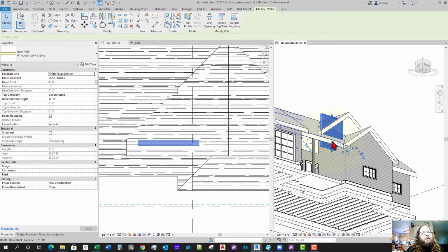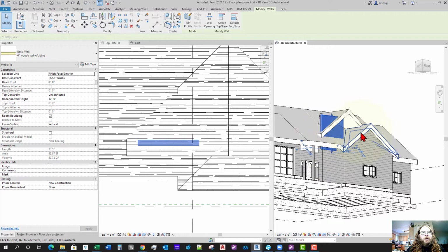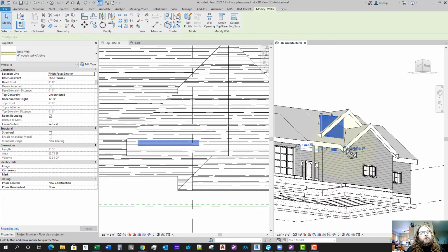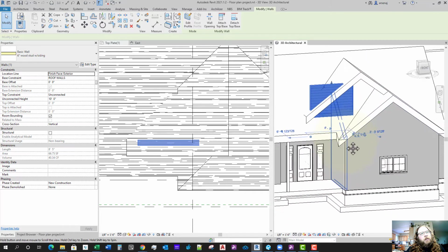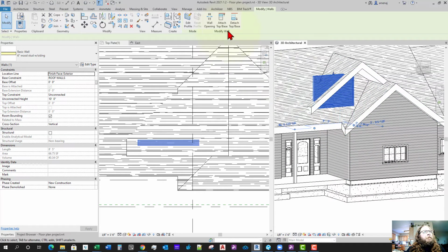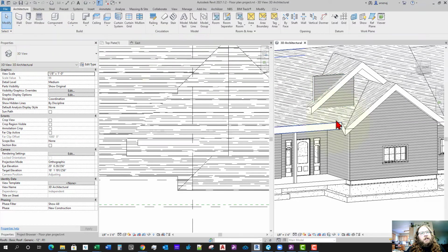And I'm going to attach this bottom to this roof. Basically, they'll just balloon frame in here. So I'm going to attach top. But instead of attaching the wall to the top, I'll uncheck this and attach it to base. And then we'll pick this roof, and it'll attach the roof to the base here. For some reason, it only did some of it. So let's see. To detach, you pick detach with the wall selected, and you can hit detach all.